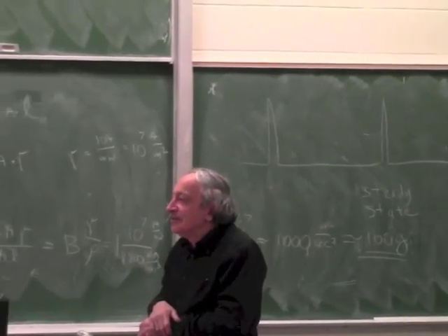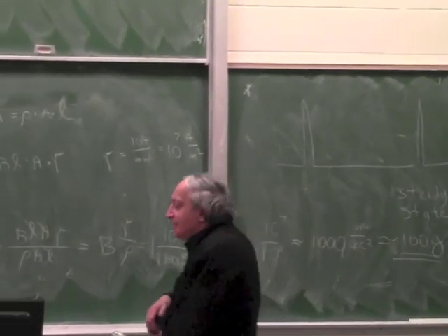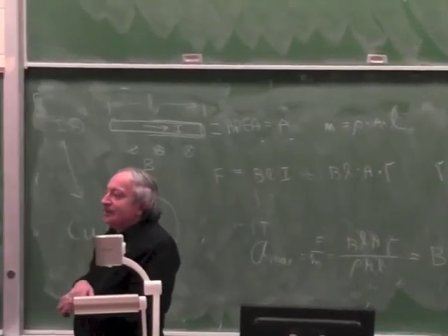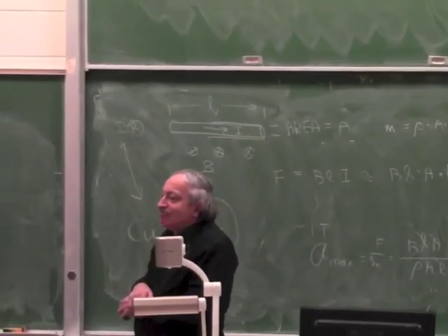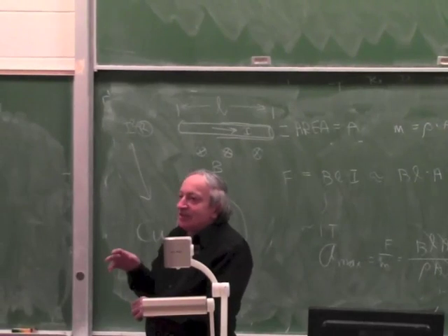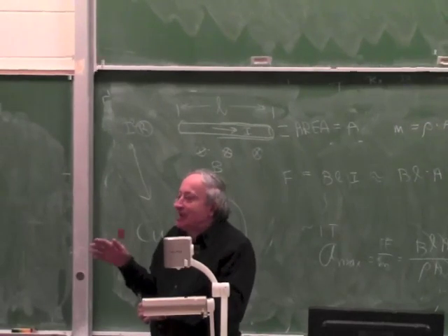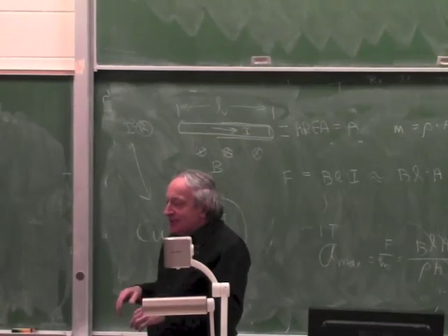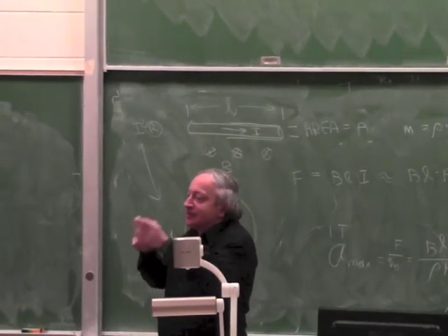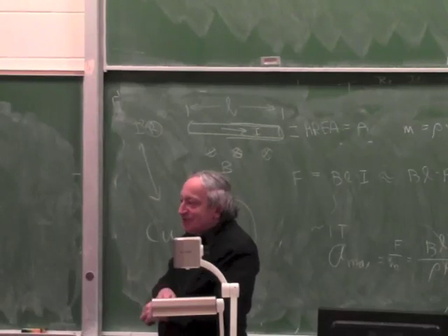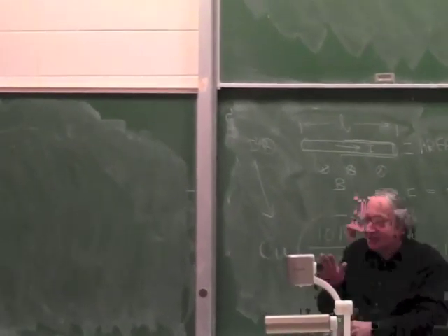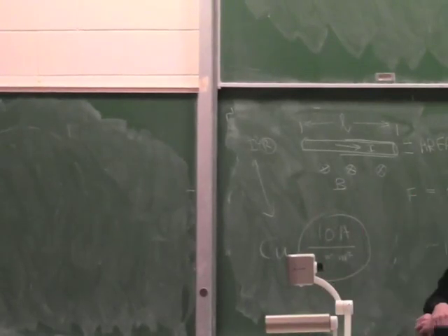The tension limit of the insulation material? Say it again? The maximum tension you can go between the 2 layers of insulation? Again, I can get around that. You're talking insulation limit, but I can get around it by making it with very high current, very low voltage. Let's say I make a coil which only has 1 or 2 turns, and I drive it with thousands of amps. So there's very little potential difference. So this I can get around. This is actually not a real limit.